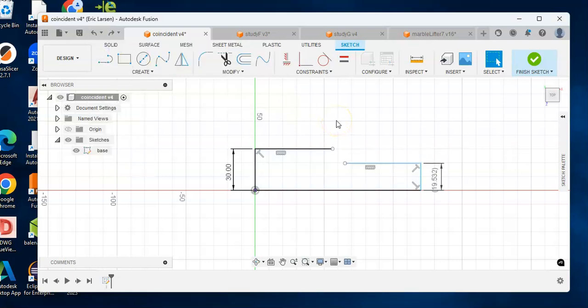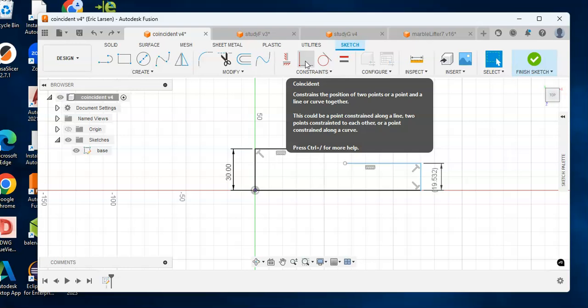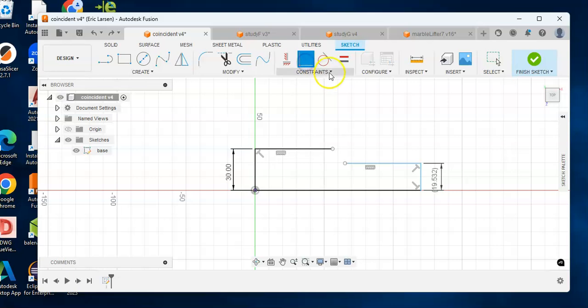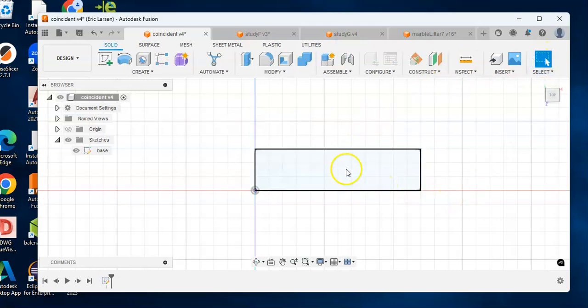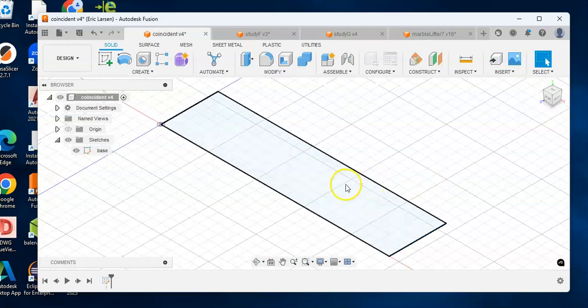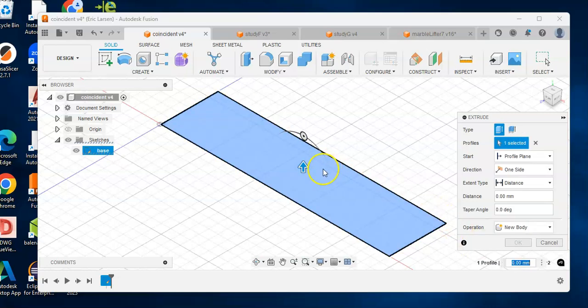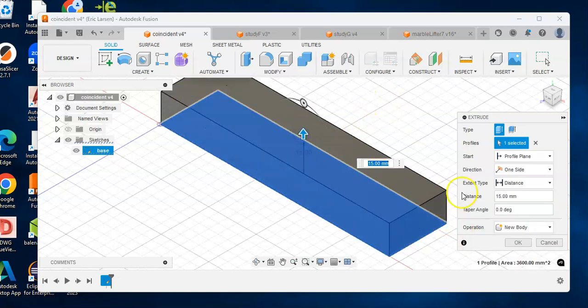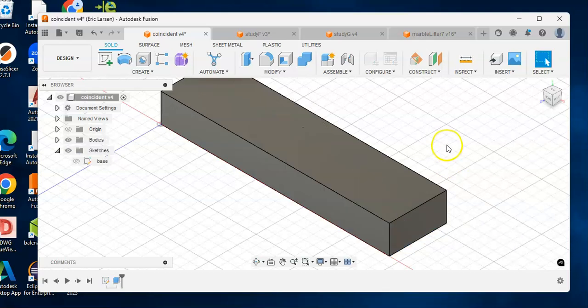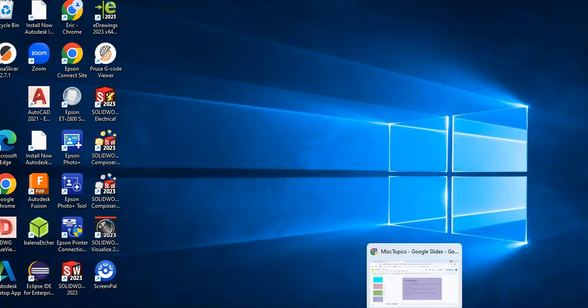And the other thing about the coincident constraint is that you have a nice shortcut here that it's just faster to click here than it is to pull down constraints. And so we go click, click, done. No sweat. All right, finish the sketch. We're all done. We can pull out here. We click here. We see that we have a profile. If we hit E for extrude, we could extrude this profile, and it would be really cool. Okay, very nice. Okay, that's the coincident constraint click pattern.